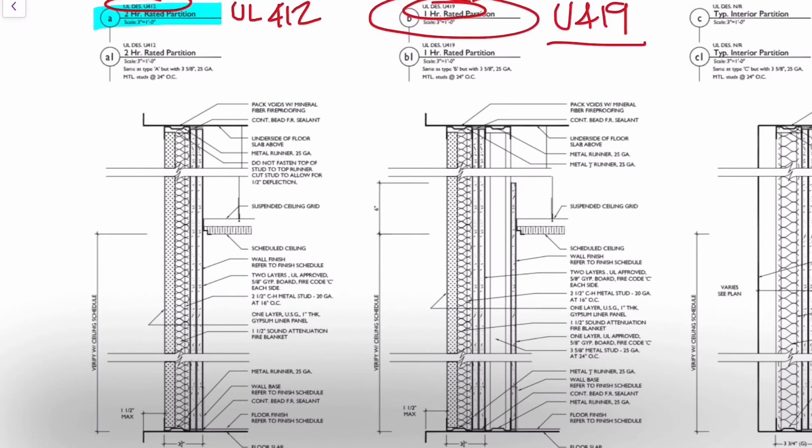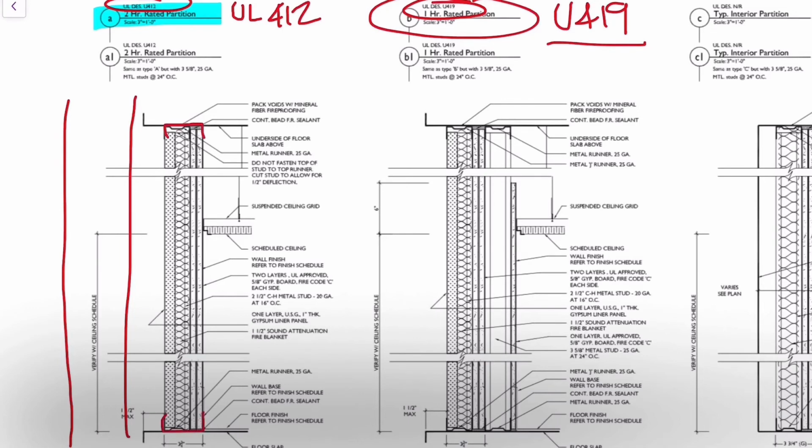In the case of this wall, you would have a duct here, and this wall is specifically designed so that the contractors working on it can't really get to this side of the wall because this duct will already be there. So they have a special kind of track and a special piece of drywall that goes on the inside, and they're able to tape and sand that, and then apply the rest of the wall to it.